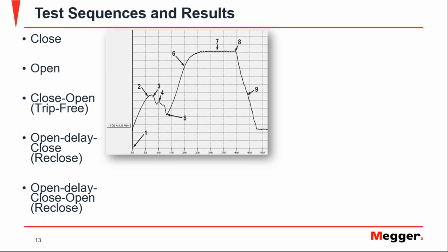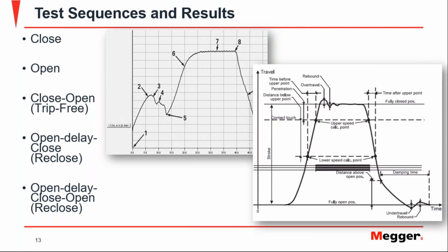And what do you get? Well, first of all, because you are connected to the control, you are connected to the coils, and you are sending commands to those coils to operate, you get the coil current. So this is the representation of the coil current. And then you would get another set of results. Here, you see the schematic of the contact closing. You see these 3 thin lines here. That means the breaker is open, and this is the moment that the breaker closes, and it's represented with thick lines, and then the breaker opens again.